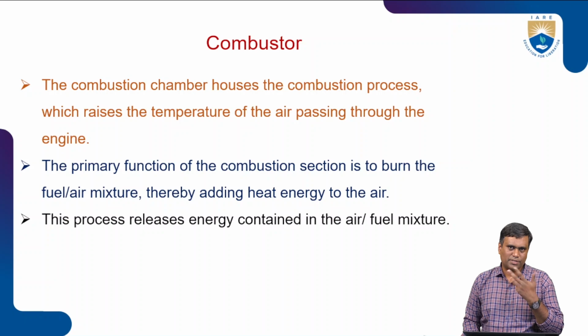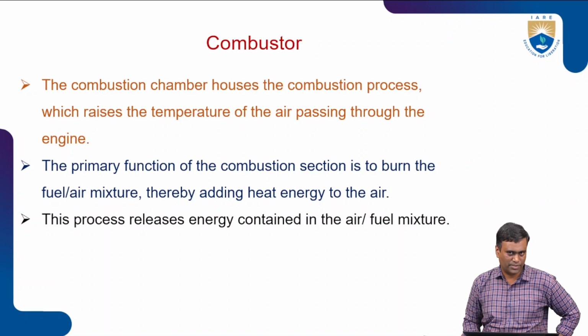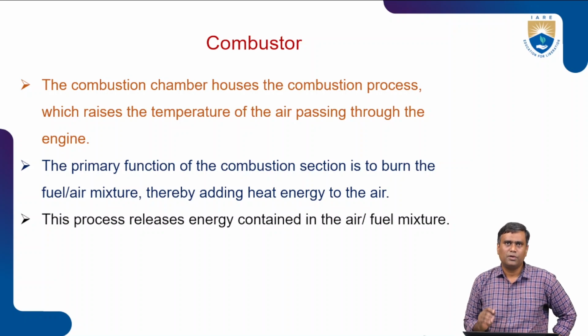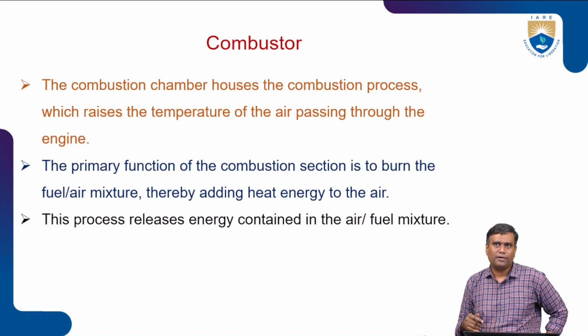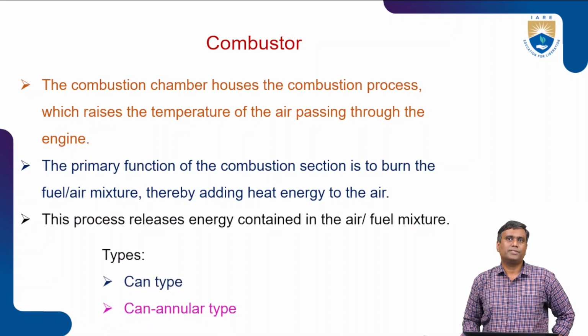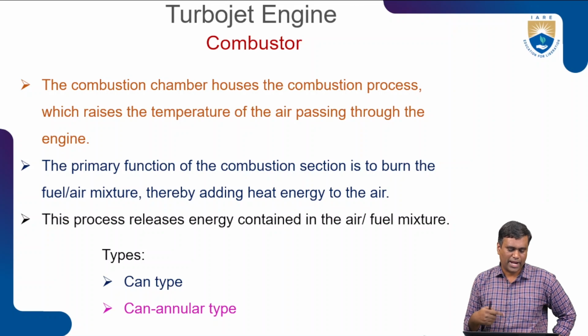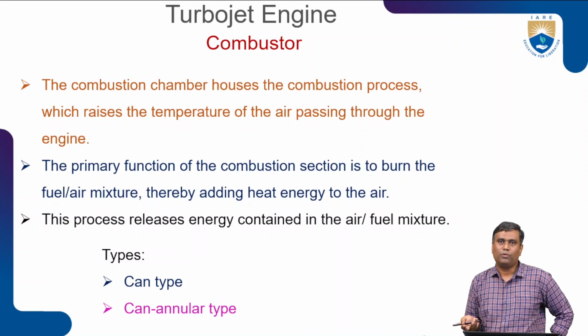That combustion process will result in an increase in the temperature of the mixture passing through the combustor. The primary function of the combustion section is to burn the fuel-air mixture, thereby adding heat energy to the air, and of course this releases the energy. Next, this exhaust of the combustor will be transferred to the next component, that is the turbine, right?